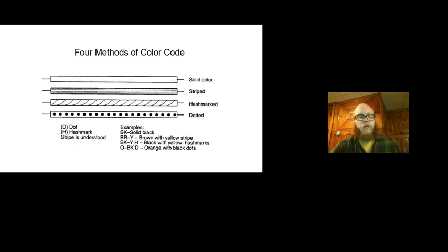My father-in-law works for Caterpillar, and on every one of the factory wiring harnesses, all the wires are pretty much the same color, but on the wires they have written what the circuit number is. So if you look at a diagram and it says this is circuit C25, and you find that wire, every few inches or so would be C25, C25, C25.